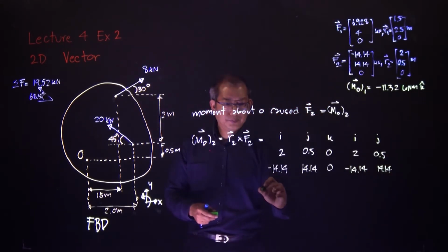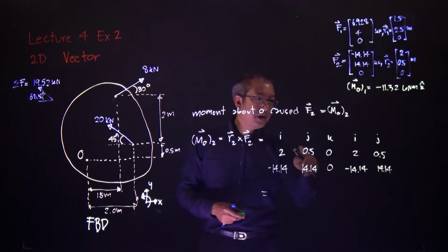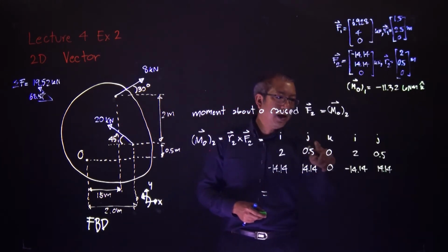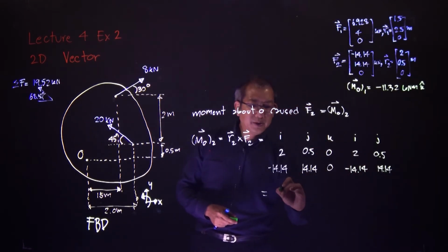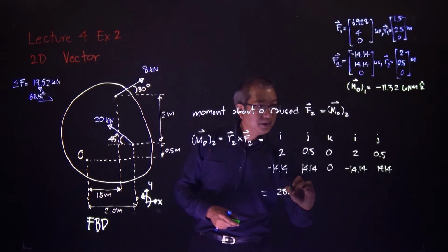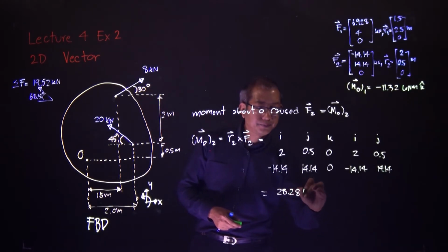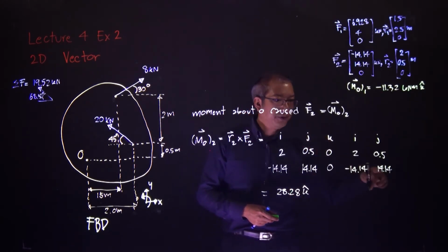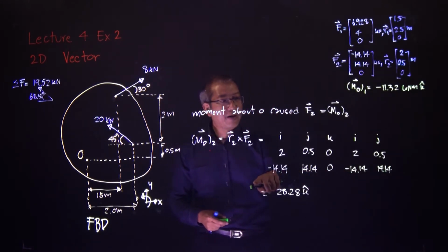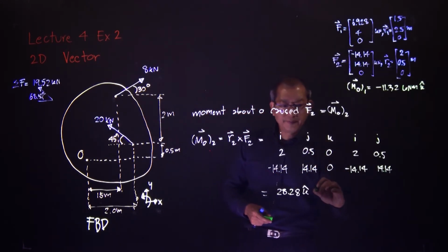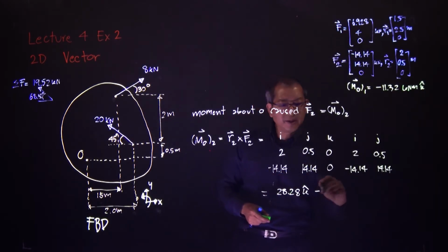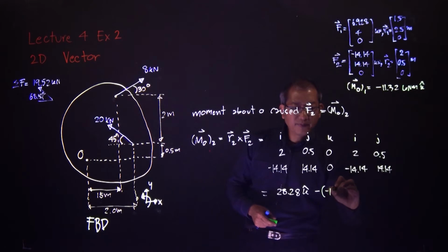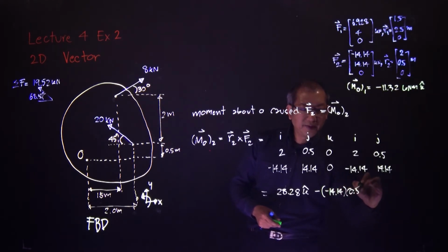Okay. Now, the first cross downward 0, second cross downward 0 again. Then we have that one. That one is 28.28 k, downward positive, so we change nothing. Then we have that one going up, negative of, don't forget times up is a negative 1, then minus 14.14 times 0.5 k.